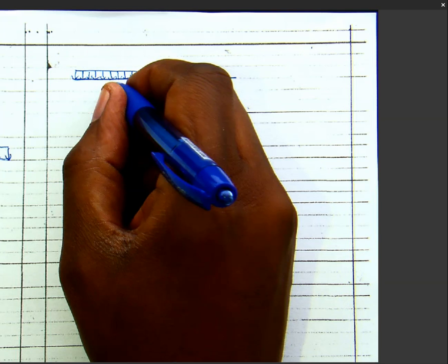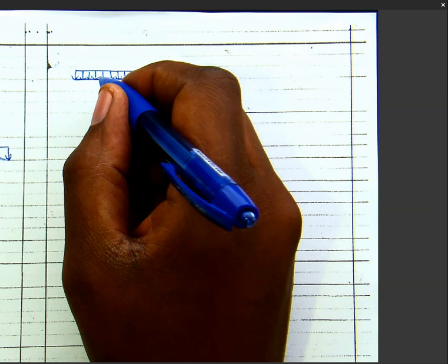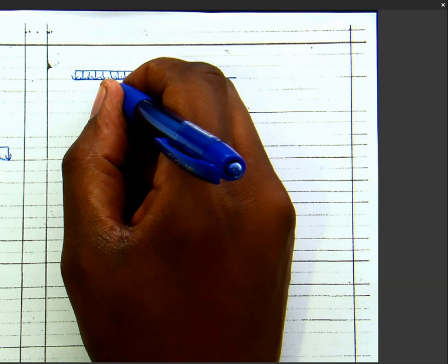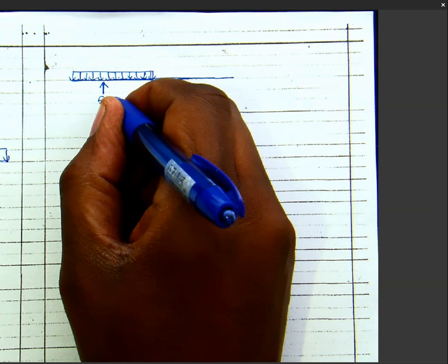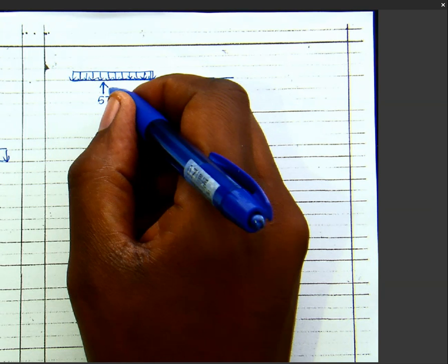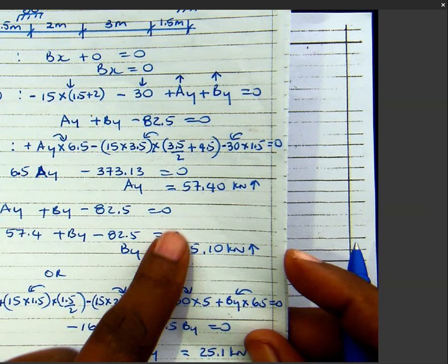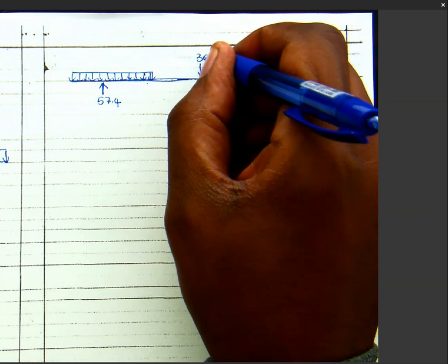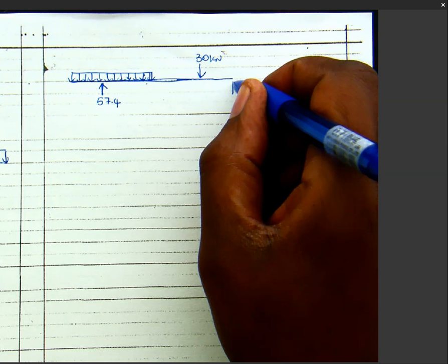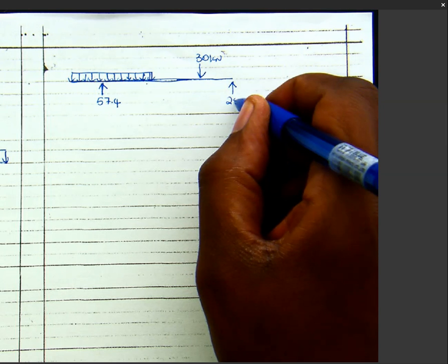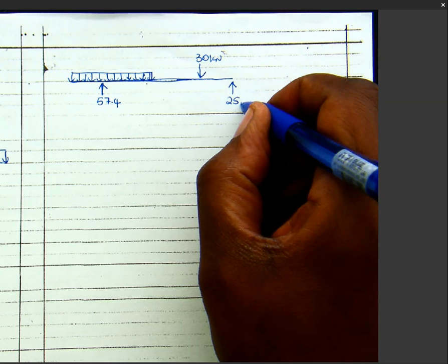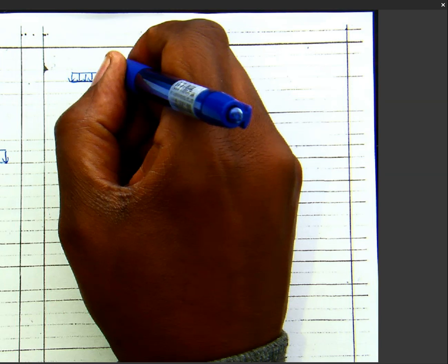So now you know. So we calculated the reaction at A, and there's my reaction at A, 57.4. That was from there, guys, there's 57.4. And then I've got my point load there of 30 kilonewtons, and then I've got my vertical reaction at B of 25.1. The load was 15 kilonewtons per meter over,